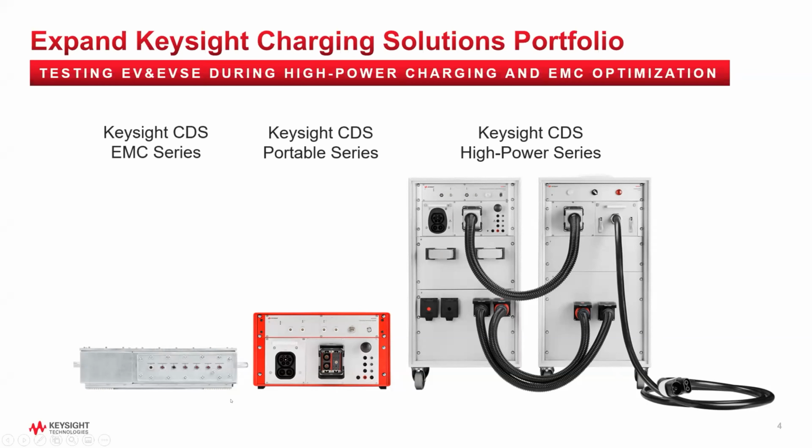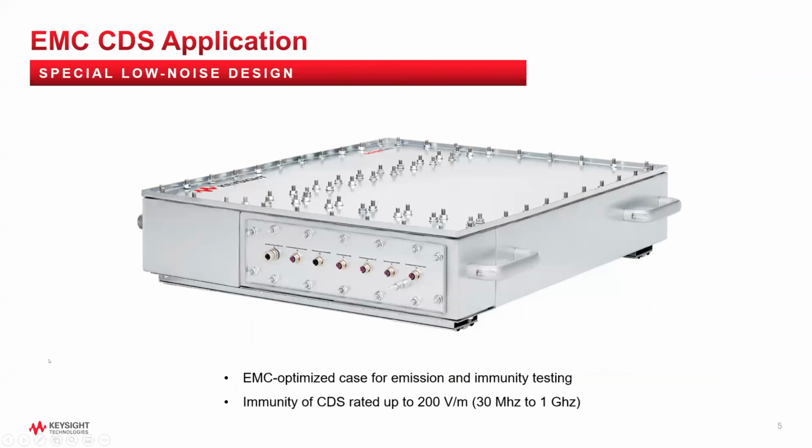We're going to focus more here on the EMC version down here in the corner. And that's what is shown here. This is what it looks like. It's an EMC optimized case for emissions and immunity testing. And the immunity of the CDS is rated up to 200 volts per meter between 30 megahertz and 1 gigahertz.